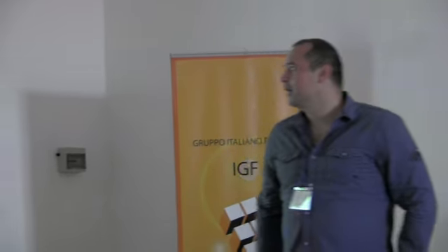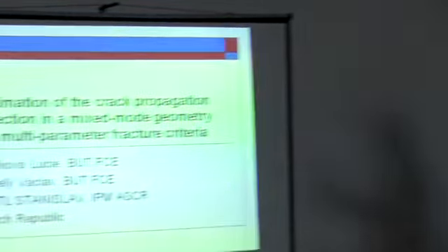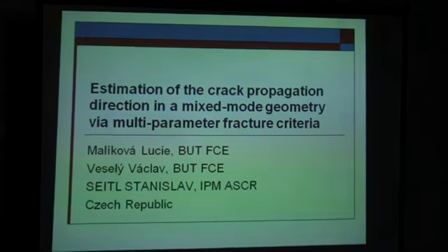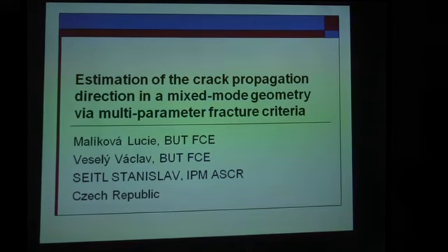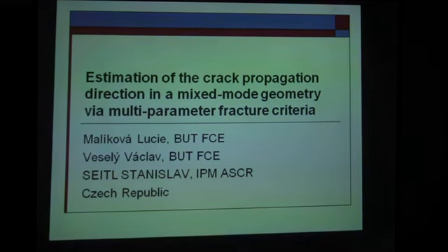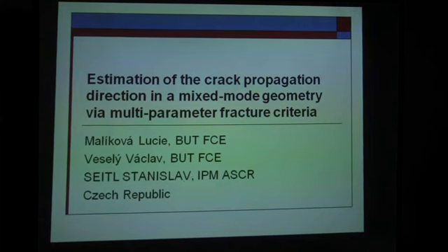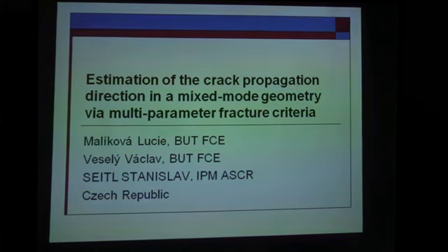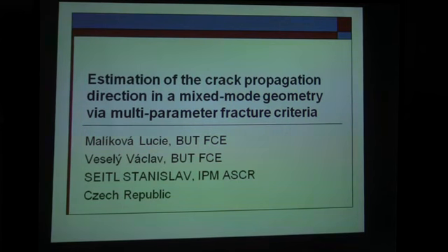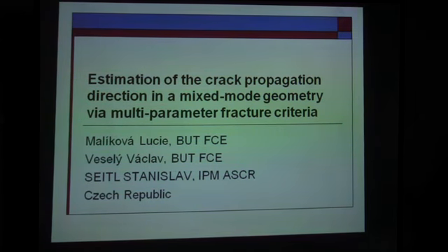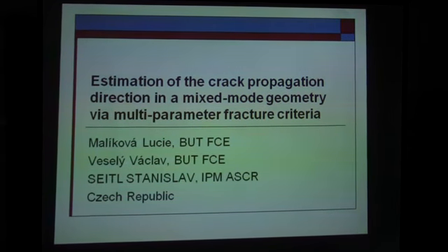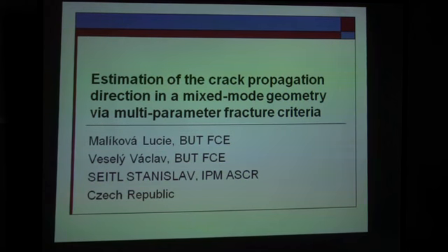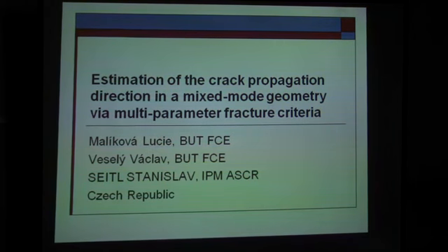Today I prepared a short contribution about the estimation of the crack propagation direction in mixed mode geometry via multi-parameter fracture criteria. I think every one of you knows classical fracture mechanics, where we use the first term of the Williams expansion. Some of us use two-parameter fracture mechanics that use the stress intensity factor and T-stress.